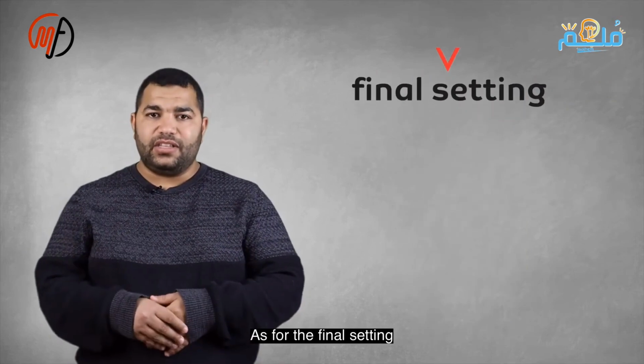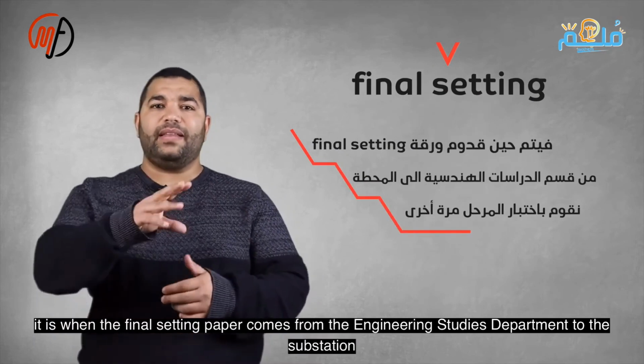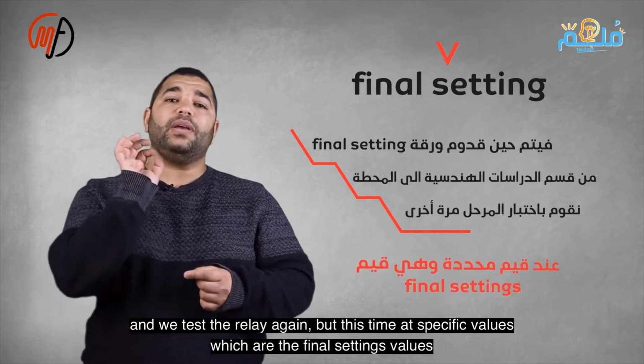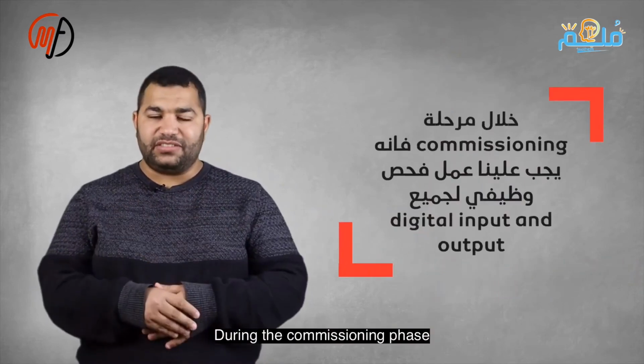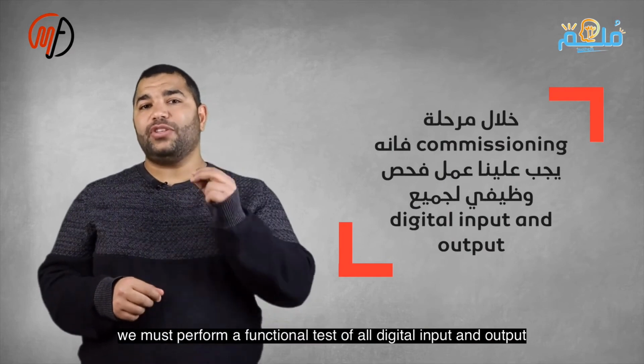The final setting occurs when the document from the engineering studies arrives at the station. We retest the relay with the final setting values. During commissioning, we conduct functional tests for all digital inputs and outputs. We also perform metering tests for current and voltage inputs, and pickup and timing tests for protective functions.